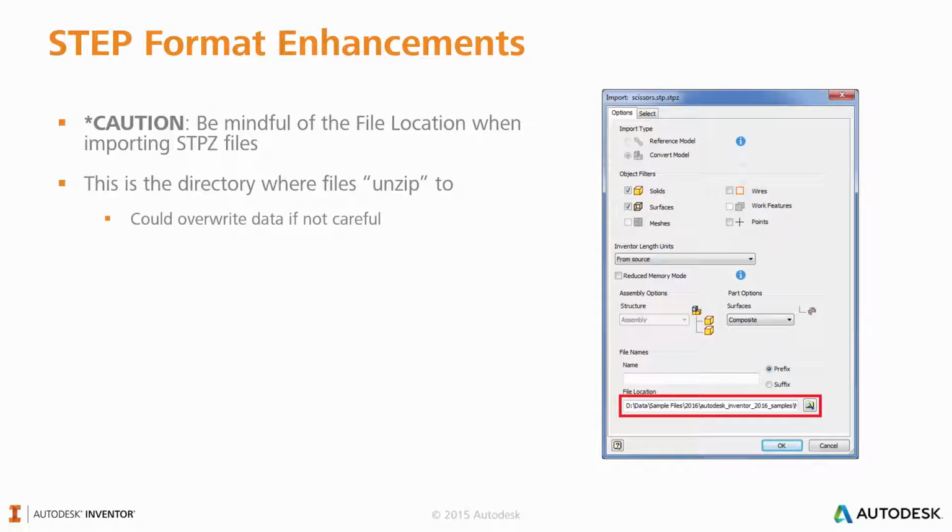And further to that, you'll also notice that we can now import STEP Z files. The only real proviso to keep in mind in this instance is the dialog box associated with the file location. In essence, this is where all of those files will be unzipped to. It's important to remember that if there are files existing in that directory, the process of importing the STEP Z file will overwrite those files that have the same name. So keep that in mind when you go to import your STEP Z files.